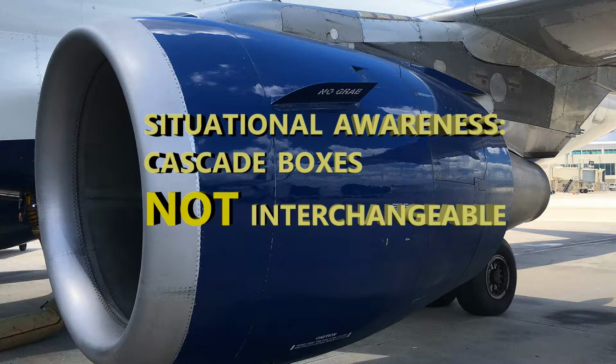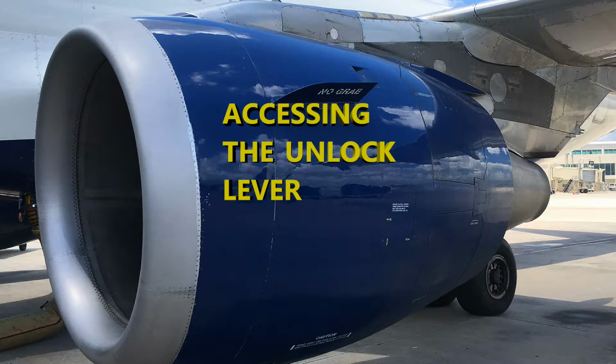The protective cover must be open, obviously, to access the unlock lever. There's an unlock lever. And remember I said the track lock, there's one track lock that's installed on the latch beam. And that has the unlock lever that's a manual type, and then you have a hook as well. There's also a visual indication pin that you can use. It actually gets pushed, and that just lets you know that the latch access panel is closed. So you have some indications there when you're needing to access things.